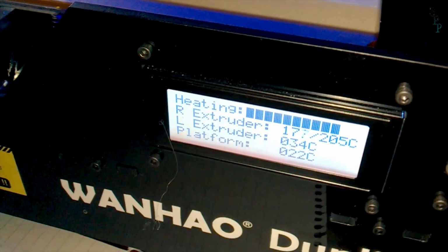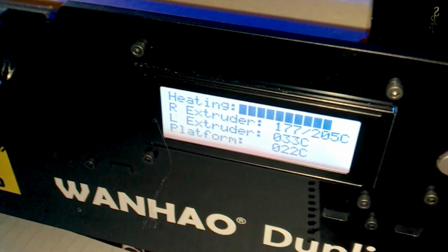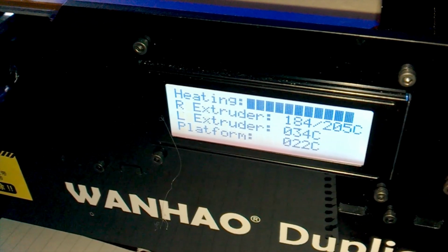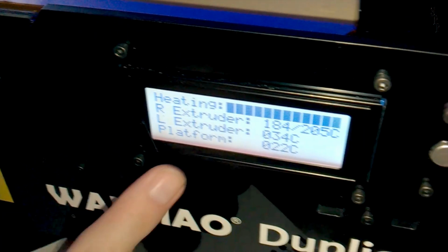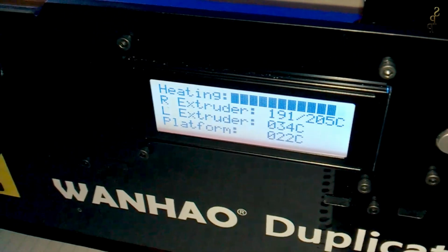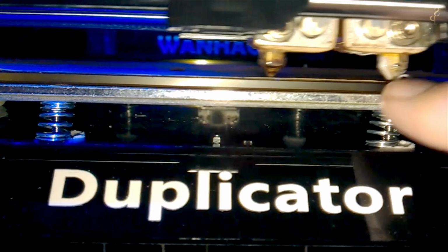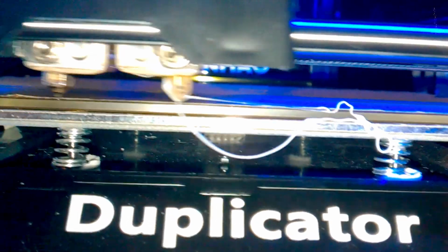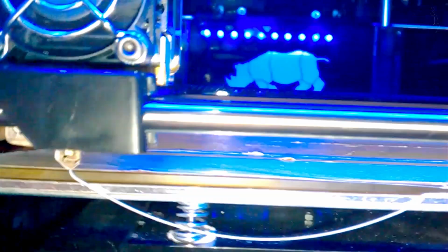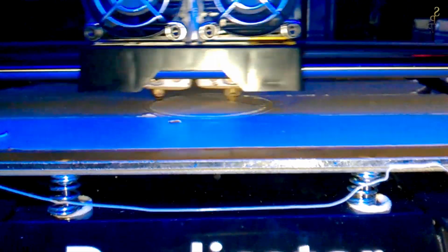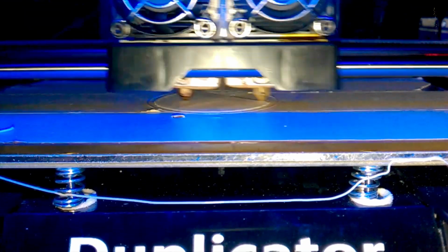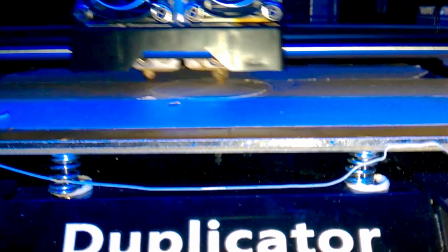Once you've got the build plate level, it will usually hold its level for a while, but at the moment, depending on your printer, my printer has plastic arms for the build plate, and so they vary a bit with temperature. So here it goes, having another go. Be careful if you do what I just did, because obviously that print head's over 200 degrees centigrade. So you can see here, it's drawn a circle and it's now filling it in.